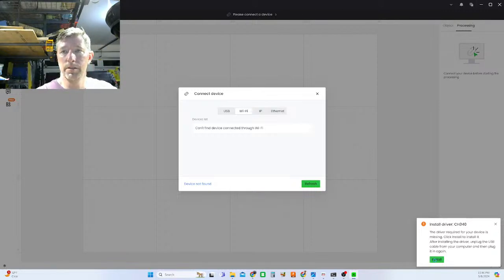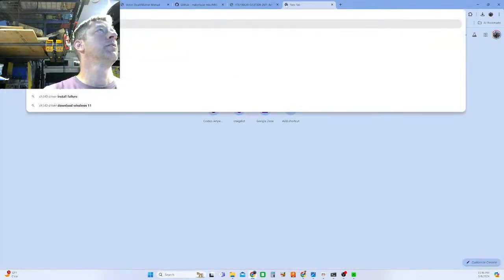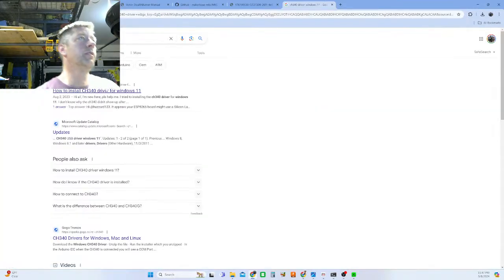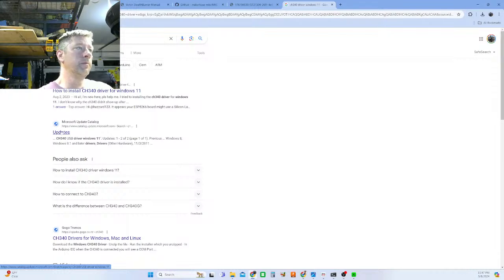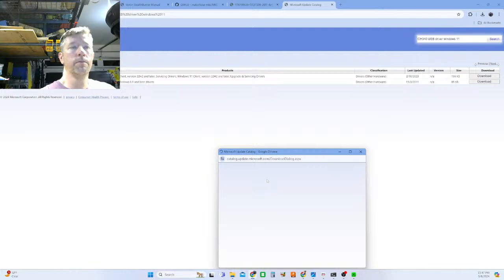That's funny, it did not install. So let's pull up another window and find the CH340 driver. Windows 11. There's other hardware, catalog update. Windows 8, 8.1, Windows 11, 22H2. Download.